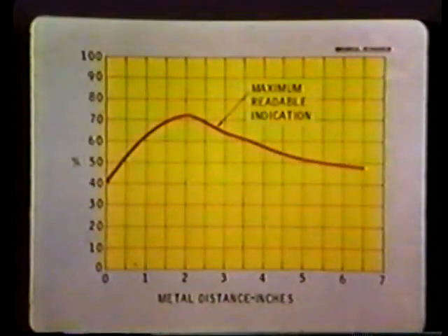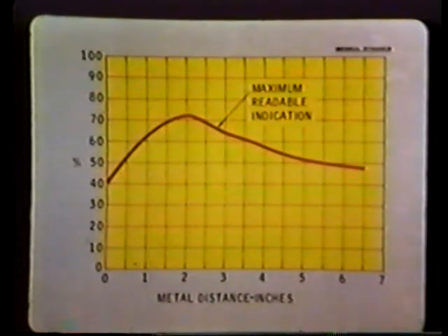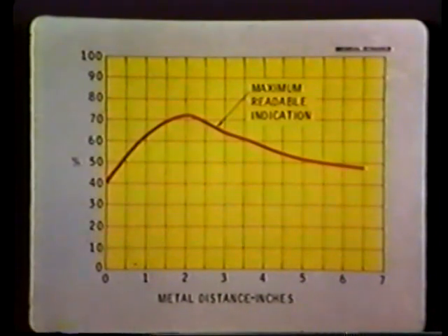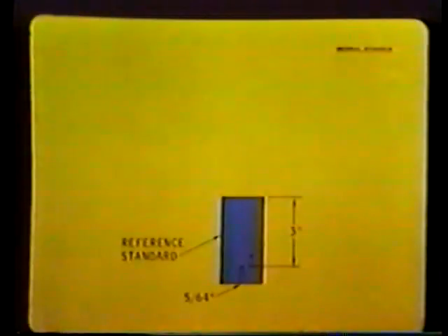Ultrasonic test specifications often require us to plot distance amplitude curves for each test instrument, transducer combination, for use later in checking calibrations. These curves must be traceable to the test instrument and transducer used, and include such information as instrument control settings, water travel distance, and so on. In plotting a typical response curve, instrument gain first must be standardized. As an example, let's start with a reference block containing a 5/64 inch diameter flat bottom hole, 3 inches metal distance.